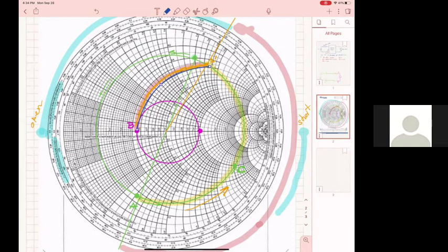All right? The distance for the line, which is the yellow. The distance for the stub, which is the pink. I have a question about that. Yeah. So when you take the distance for the line, it's from A to A prime. Yes. But when we take the length of a stub, are we supposed to find the complex conjugate of A prime? No, if it's shunt, no, you stay with admittances all the way.